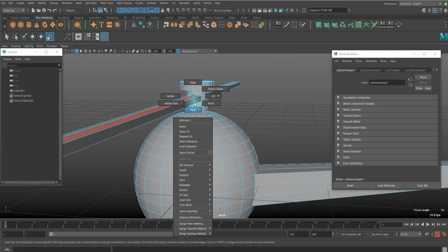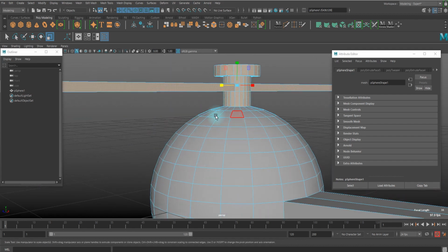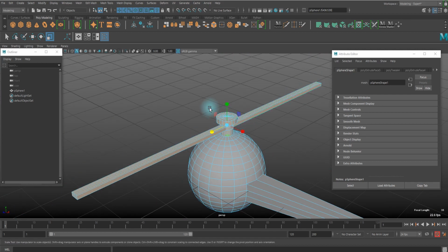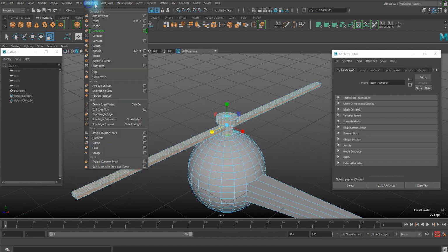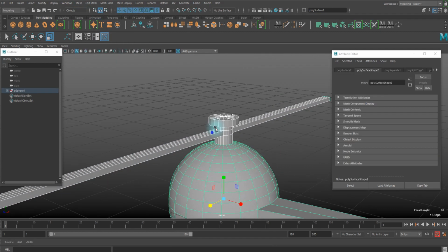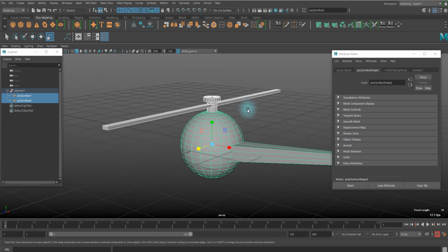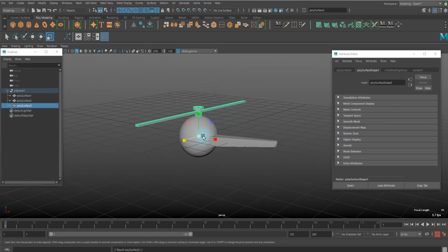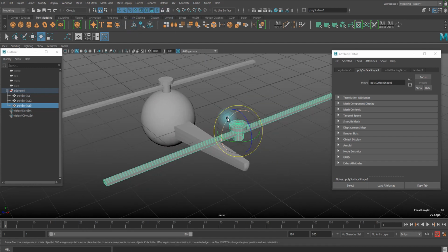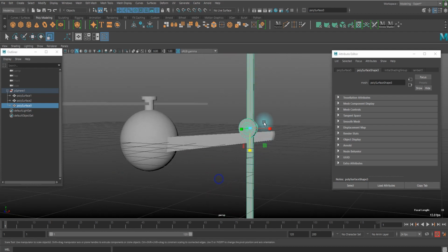And what I'm gonna do next is like those other parts, and we can actually detach it and separate. I got these two parts here. Actually, we can get rid of history, and let's just duplicate this part and center the pivot and rotate and place it right there.